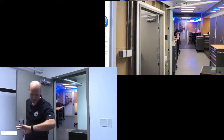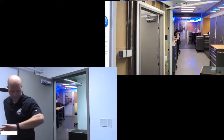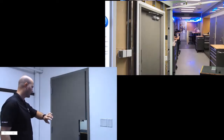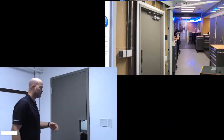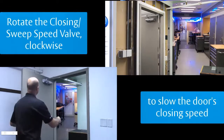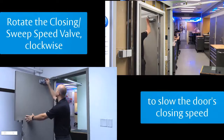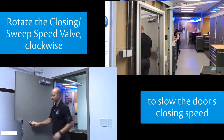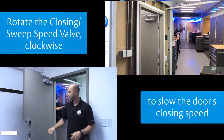and actually time with my watch. 2, 3, 4, 5, 6, 7. It's a little fast, so we'll slow down our sweep or our closing speed. Give that just about a quarter turn. We'll see what that gives us.